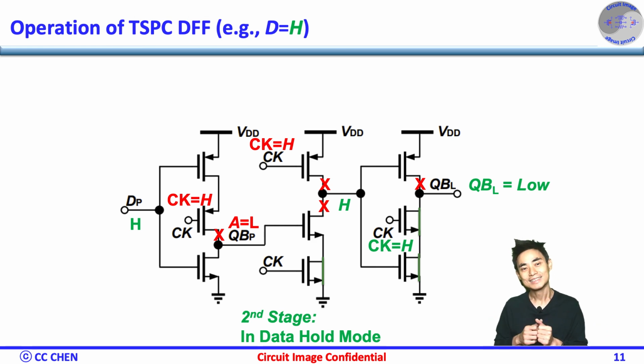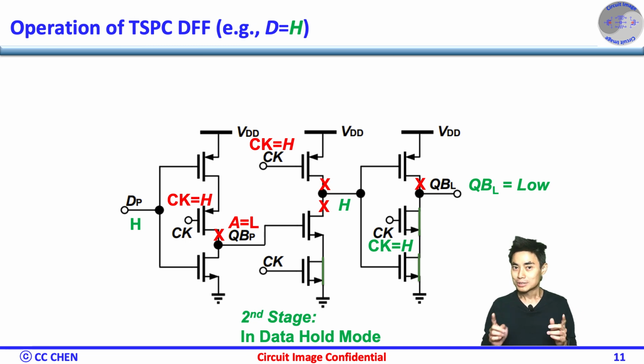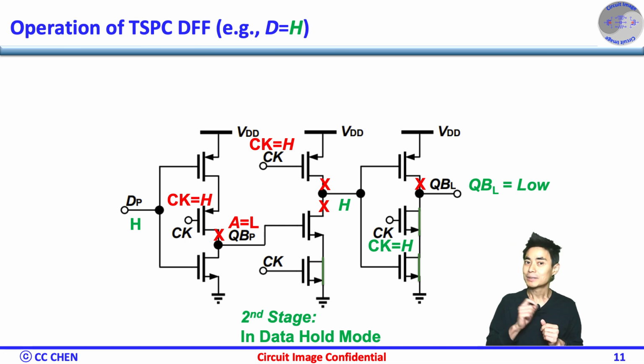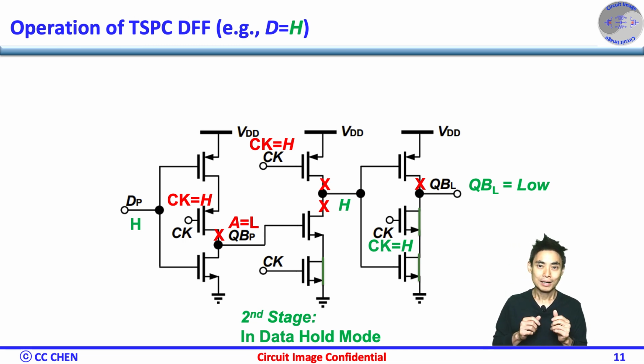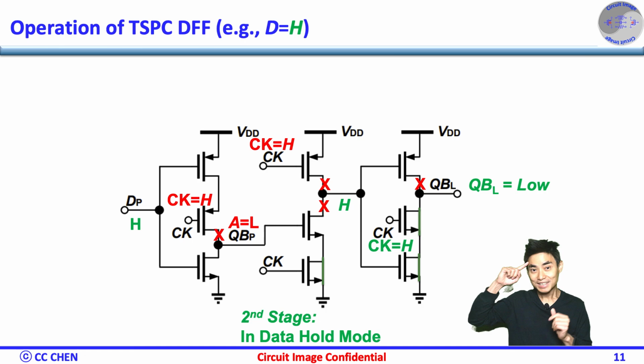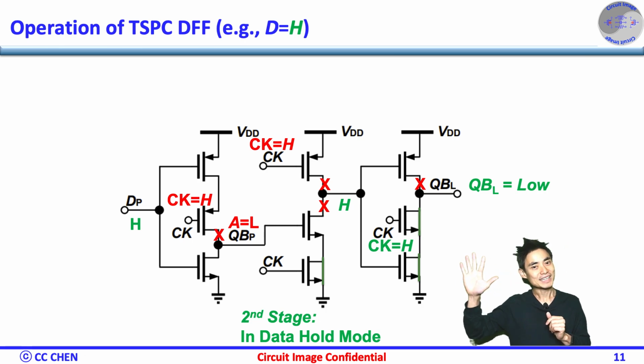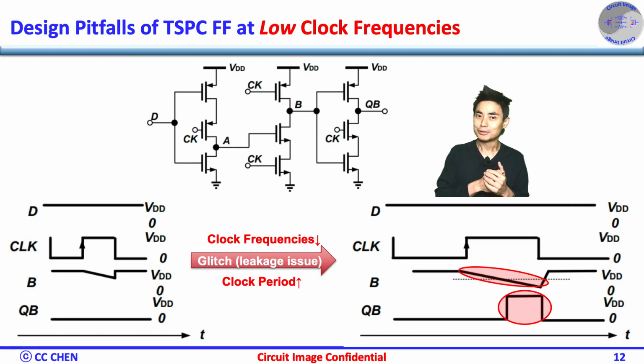After understanding the TSPC flop operations, we should appreciate all the charge dynamic operation to speed up the data sampling and transfer. But there's a fundamental design pitfall. Think about the leakage issue for 5 seconds. Bingo, the TSPC flops will fail